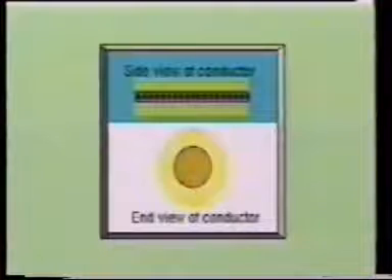When a current starts to flow through a conductor, a magnetic field will start to expand from the center of the wire. These lines of force will move outward through the conducting material itself and then continue into the air. As these lines of force are expanding, they will cut through other conductors of the same coil. This will induce a voltage into these conductors.